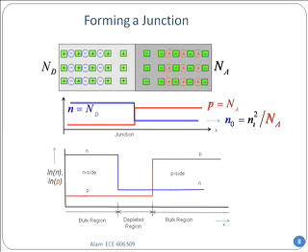So, if you look at the end concentration, what will happen? This is how it will look. Do you agree with this? The number of electrons, which are the circles, sort of stays flat up to a point, then it drops down. It drops down because there are fewer holes on the other side. And similarly, the red holes essentially stay up to a certain point and then drop down away from the junction, right? A little bit away from the junction, the carrier concentration has dropped down.